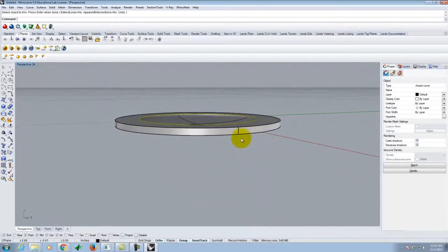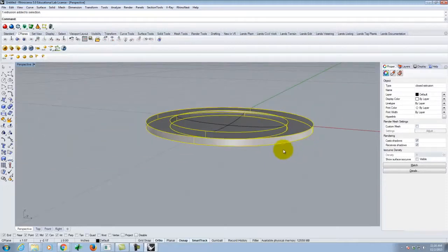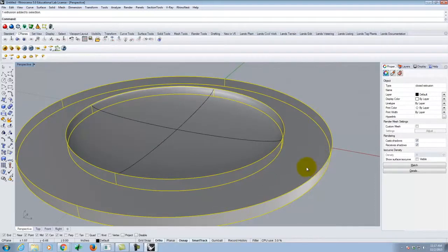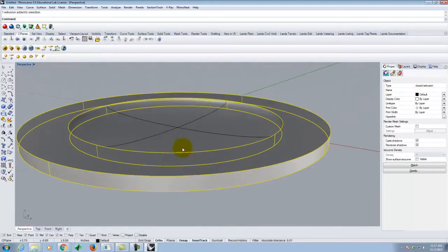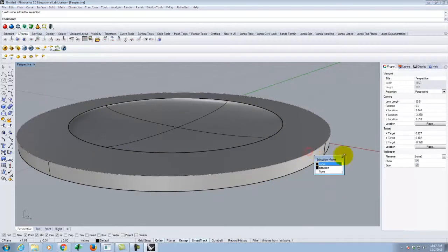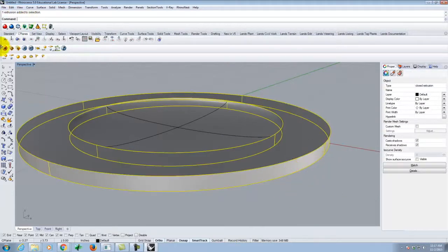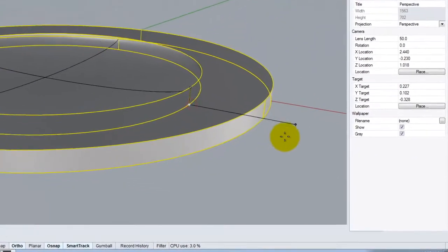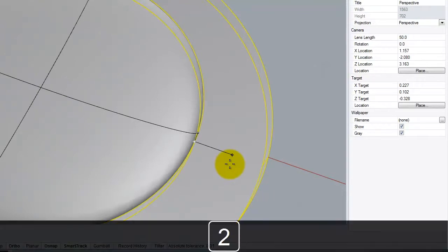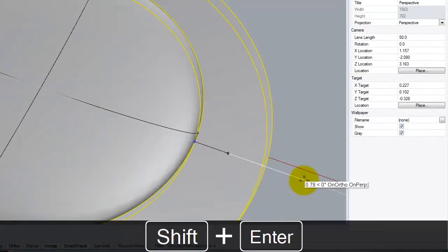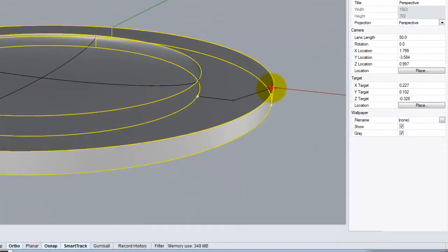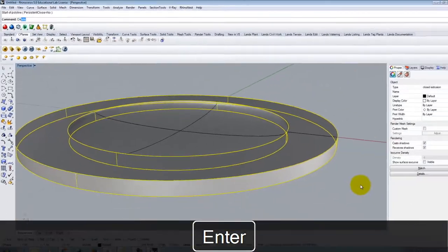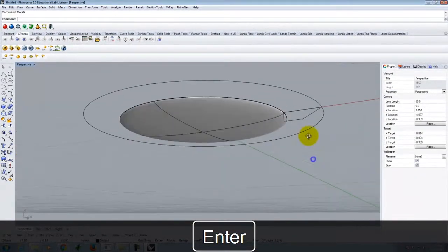Now, I could probably add a little bit more finesse. This is a rather generic or ugly piece of trim. So let me go ahead and modify this trim to make it a little bit more attractive. Let me just use a polyline here. Go down. Let's go over maybe 0.25. Like that. Something like this. Get rid of that. And then I'm going to just sweep this profile.